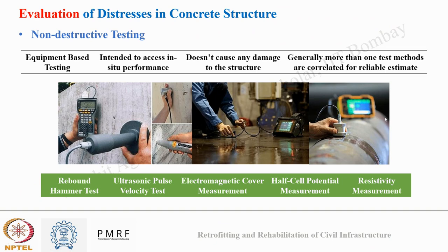Okay, after semi-destructive testing, we will now discuss non-destructive testing. The key features of these tests are: these are equipment-based tests, which are intended to assess the in situ performance of concrete or infrastructure. They don't cause any damage to the structure, as the name suggests, and generally more than one test method is required, correlated for reliable estimates.